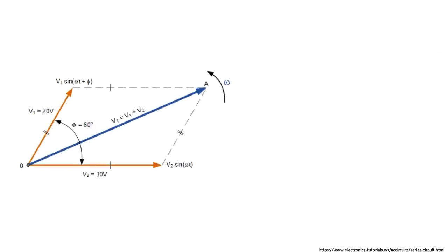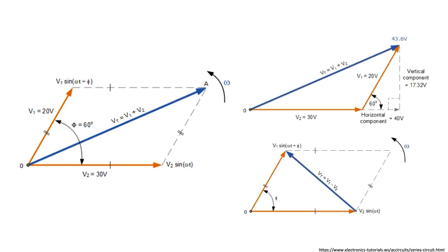Graphically, we would add the phasors the same way we add vectors. That is, we either draw the resultant phasor from the parallelogram method, or we connect all phasors head to tail, and the resulting phasor would be the phasor corresponding to the source voltage. Again, the reason for using this and not simply using algebraic addition or subtraction is because the phasors are always expressed in terms of the amplitude and the phase angle of the phasor, and phasors are complex numbers.